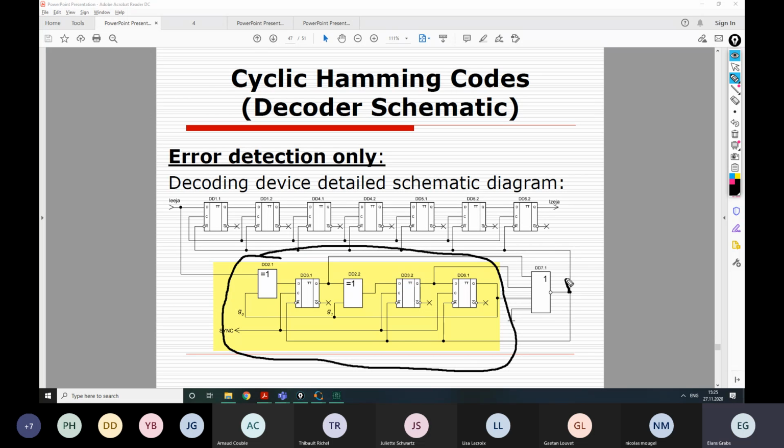And its output signal is connected to the reset port of the triggers. Here is the reset input. So if we send 0 there, then contents will be erased and data will be discarded, right? So in order for that, we need not simple OR function, but OR with inversion here.